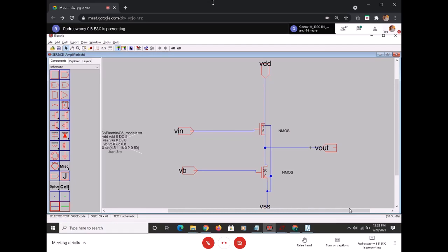That ensures that your VDS is greater than the difference of VG and VD, which is needed for saturation. Then when you do the DC analysis, varying your V in from 0 to 5 in steps of 0.01, from the DC analysis we have to find out the biasing voltage for M1 and choose accordingly. That is when exactly the V out follows V in in parallel.